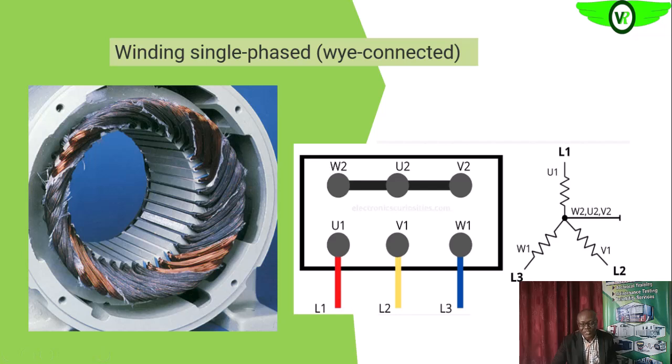Okay, so once there is an open fuse, it means that if the fuse is open on this line alone, these two other lines will be supplying voltage or power to the electric motor, while this one is open, so it could not supply, and no power will be able to return through this line.